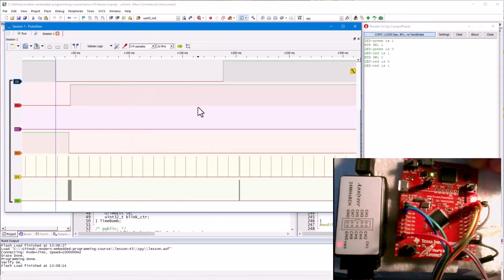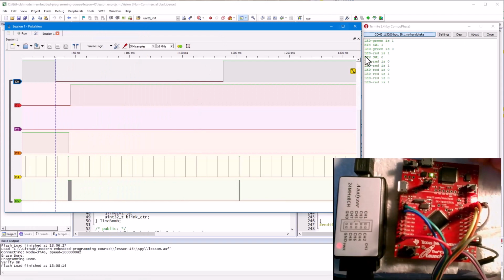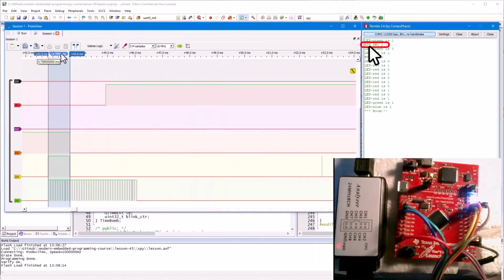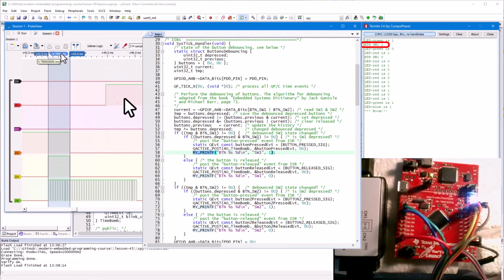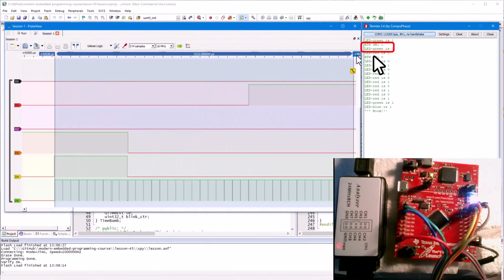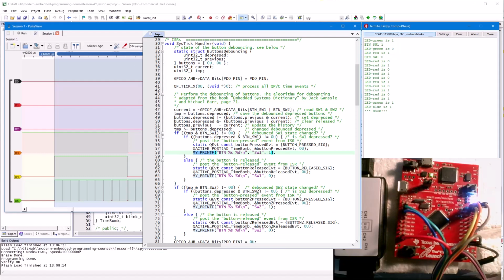The printf software tracing seems to do the job and everybody uses it. But the approach is very intrusive. For example, this simple printout took almost 800 microseconds, and the overhead occurred in the interrupt context. These three simple printouts, produced in quick succession, took over 3 milliseconds, and again they occurred in the time-critical path through the code. So, while software tracing is immensely useful and indeed indispensable, printf-style tracing is not the smartest way